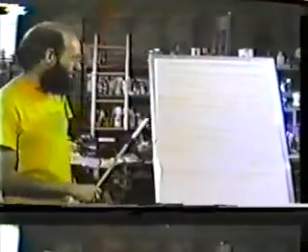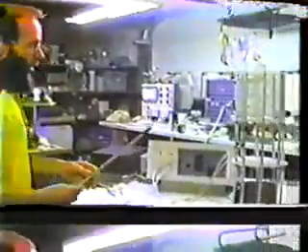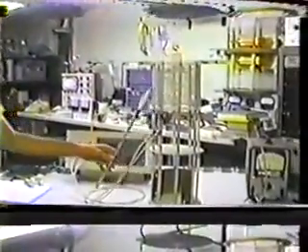So we've broken the speed limit of the velocity of light. Or you might say we might get a ticket from the relativity police in this case. At any rate, going back to our structure over here, we can see how this occurred. We're really not having transverse flow between the turns anymore, but the energy is now spiraling due to the complex quantities of induction along the wires in this direction.